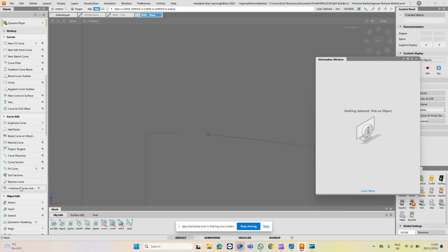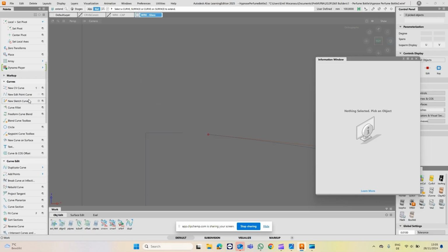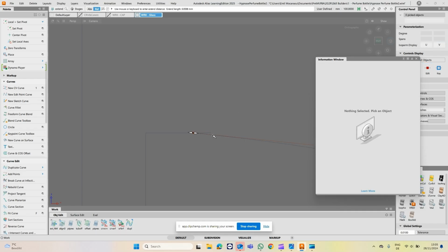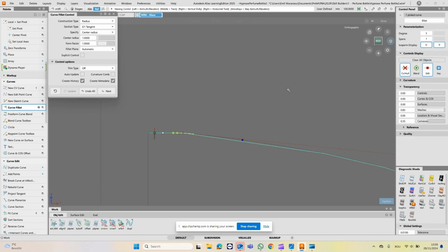finding the blend curve, or let's keep it easier for this here. We will be doing some curve fillets because everything is sitting on a plane, so it's easier to do that. It's extending and clicking Control Alt on the line, so it extends only to that line. So curve fillet between these two. And I'll get 1 mil center radius. That's that.